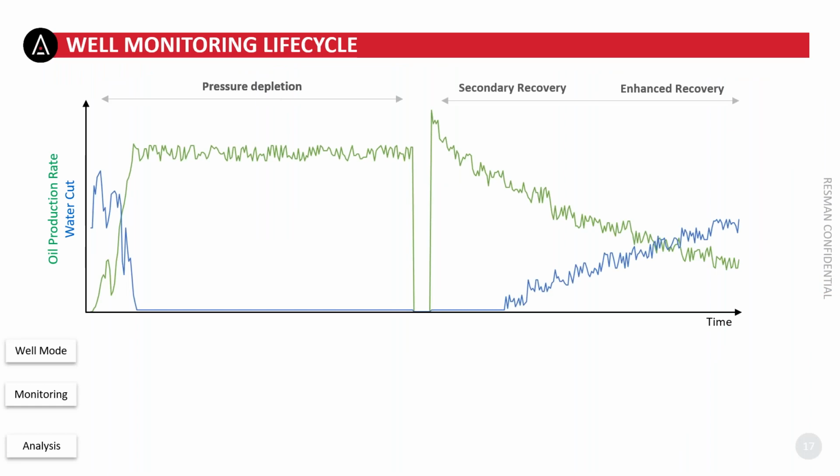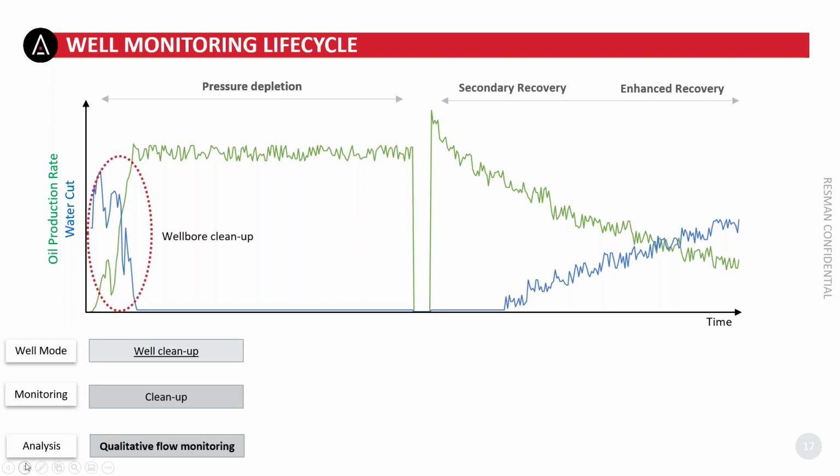Before going to the actual field studies, I would like to take this slide for explaining how the Resman tracers will actually benefit the monitoring of the entire well life cycle, and furthermore to benefit the reservoir management of the field. So we have different modes for monitoring of the well. One of them is a cleanup. So often the operator is interested in knowing whether all the zones are cleaned up or not, whether they are flowing or not. So we can also advise them for implementing extra cleanup operations where the zones are not flowing and improve the productivity of the well.